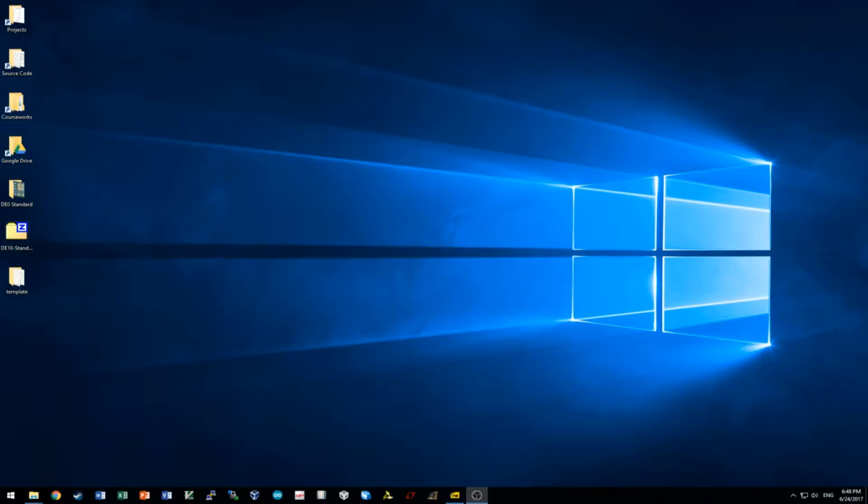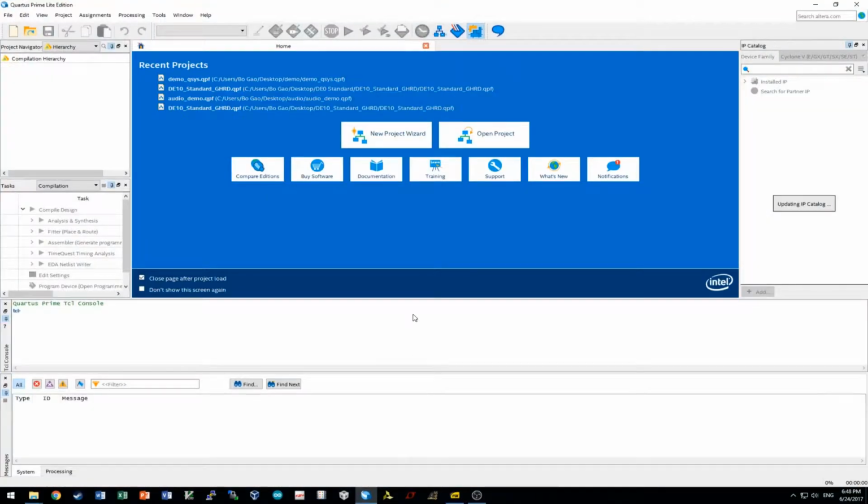Last time, in the 3rd video, we played with the official FPGA image from Terasic, and this time let's create our own image. Let's get started. The tool is called Qsys. It used to be called SOPC Builder, and now it's called Qsys, and that is the tool we are using to build our system. Generally, if you want to start a project, you open Quartus and create a new project.